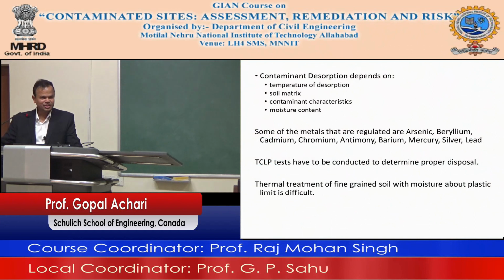The clay will stick to the inside of the desorber. The moisture requires a lot of energy to be taken out. Eventually, it might become expensive, and it might even be cost prohibitive. The contaminant characteristics, right? Like what is present in that soil. Now, if you desorb it, you have to deal with it, right? Because now it's in the air. You have to actually collect the gases, and you have to make sure you have the wherewithal to actually treat the gases. And the moisture content.